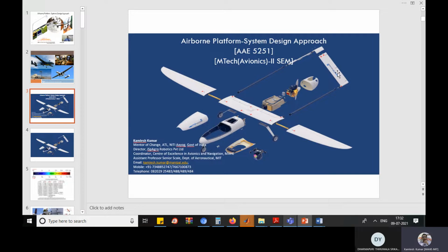This is a V shape, so you have different control surfaces deflection in this, but normally either a T or maybe an inverted T will be there. So it depends. This is a tail boom because it comes in the middle of that. Otherwise, if your motor is near the nose, then you have only a single tail part here, not a tail boom like this. So it depends on how your aircraft is designed. Based on that, you have to look at the different configurations.